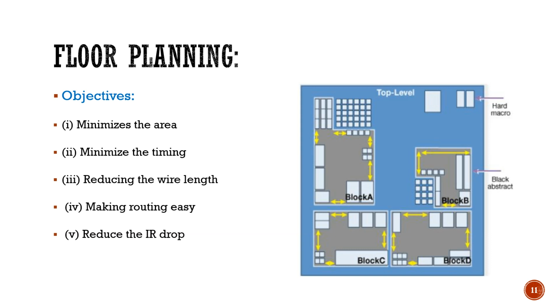So how we can place the components is, the initial step that is involved is, we need to create a rough sketch. Rough sketch in the sense, where to place the components. If I place a component like this, whether my area will be reduced or not. Or if I place the component like this, whether my power consumption will be reduced to a greater extent or not. So these need to be done through a rough sketch, and it is named as floor planning.